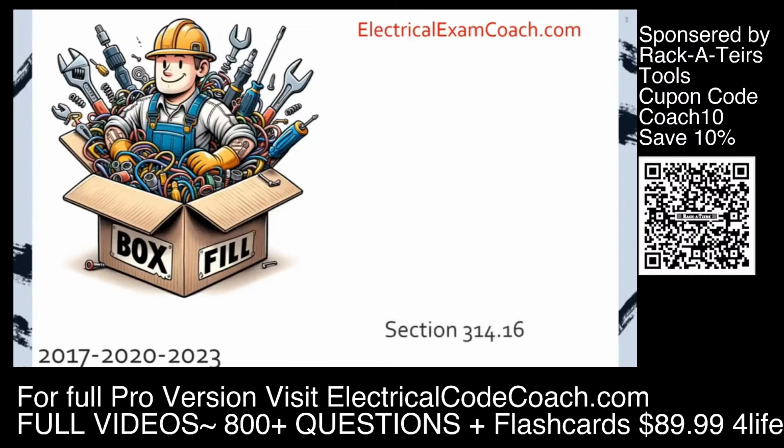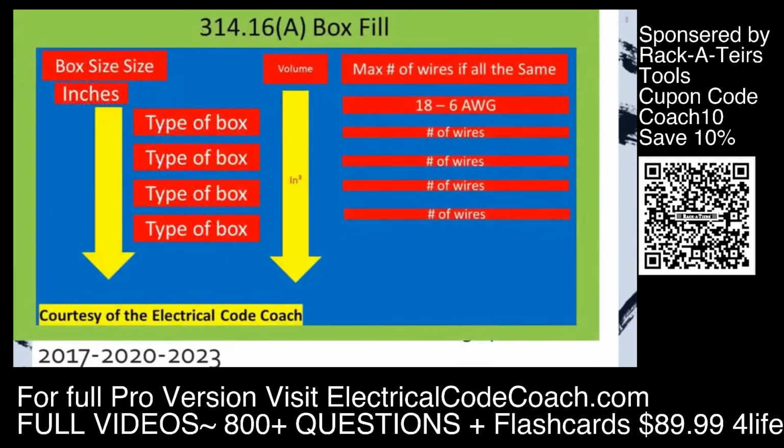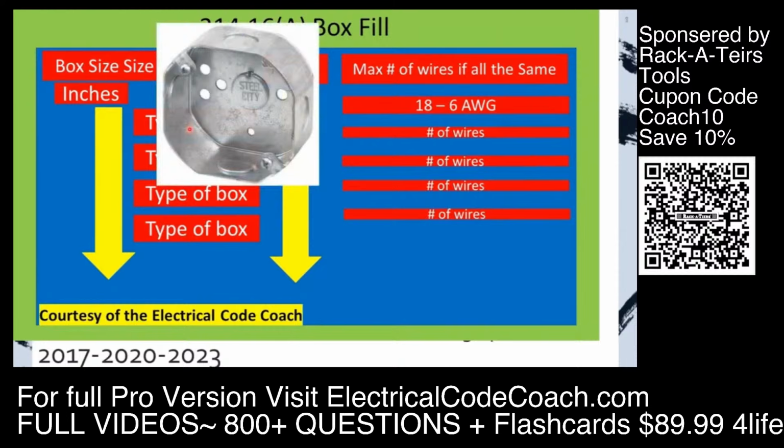We're going to be in section 314.16, and we have 2 primary tables that we're going to be using. The first one that we're going to cover is 314.16(A). Let's get to it. On the left-hand side is going to be our box size in inches. The next column over is going to be the type of box, and there are several different types of boxes. The first one is going to be the round octagonal box. A round box is truly circular, and the picture listed here is actually an octagonal box.